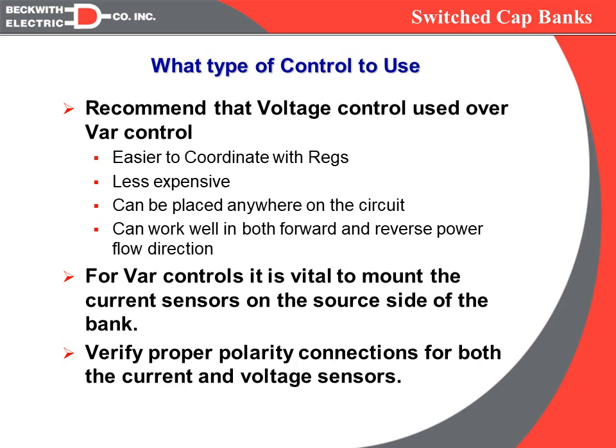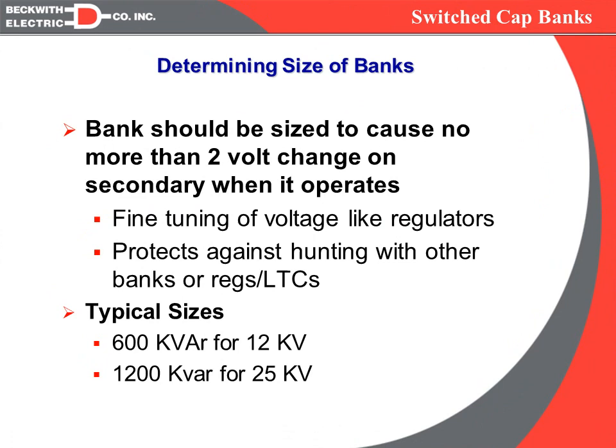So with that in mind, we're going to be talking about voltage capacitor banks. The next thing we have to decide is how to determine how many banks and the size of each bank. So starting with the size of each bank, one of our primary goals is to reduce the number of operations on an LTC or a regulator.